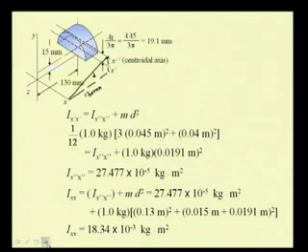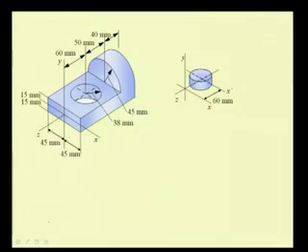Now, we can move on to the third element, that is the cylindrical feature that has to be negated, that is this cylindrical feature, which when negated gives this machine block. The centroidal axis is situated at a distance of 60 mm from this x axis, and also we see that this x prime lies in the same plane as zx, because this cylindrical feature has the same thickness as the prism feature that we have considered.